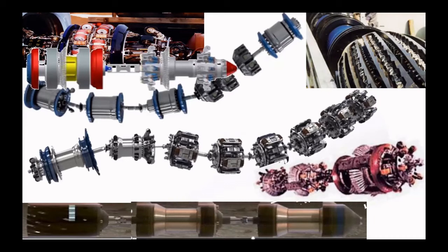Probably you don't want to run an ultrasonic tool in a gas pipeline if you're not willing to batch. Probably you need to comply with some requirements of flow speed, and probably you won't be able to use a tool because it's running too fast or too slow. Or even you have to ask yourself which vendors provide the best overall service and which one gives you the best data. These are very difficult questions, but you need to answer them before the planning of the inline inspection run.